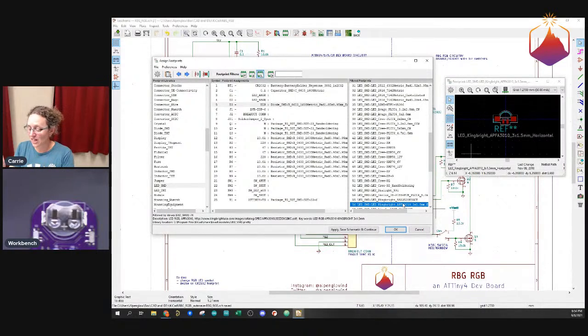And that is the most important sanity check that you can do for any circuit board, because a lot of times you'll have the right number of pads and you'll think, oh yeah, this is totally the footprint I need. And then when you get the boards, it turns out, oh God, that was twice the size that I needed, or half the size that I needed. It's completely the wrong size, even though it has the right number of pads.